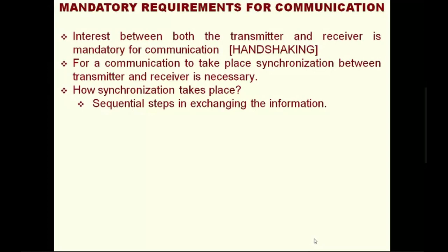So the transmitter says I am alive to the receiver through one signal. That signal is called data set ready, DSR. You can very well remember my name. My name is D. Sivaraj, DSR. So the transmitter is ready, D. Sivaraj, that is data set ready, something like that. So DSR is the signal which goes from the transmitter to the receiver in the RS-232 protocol.